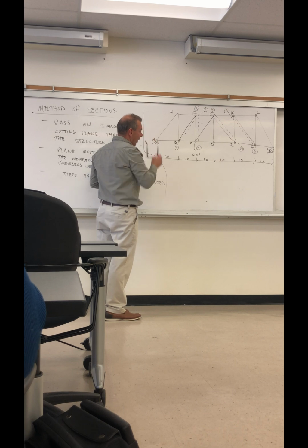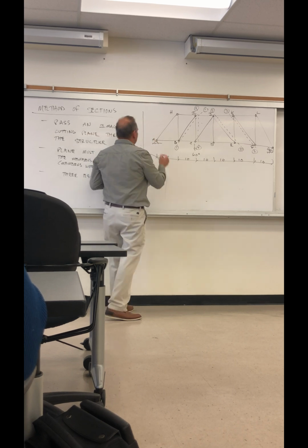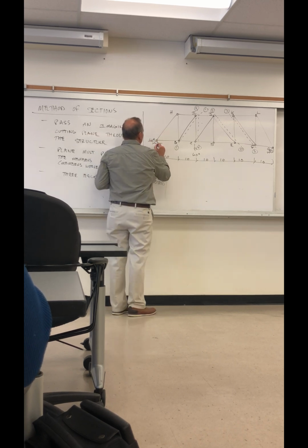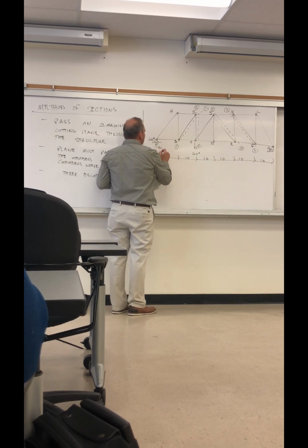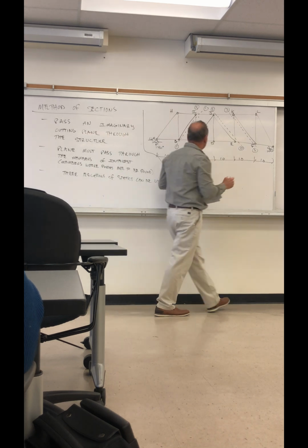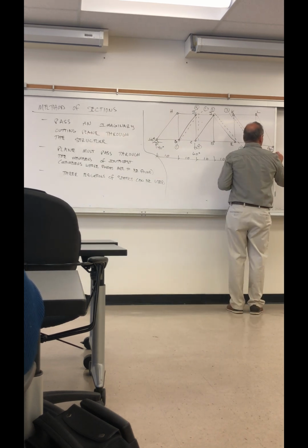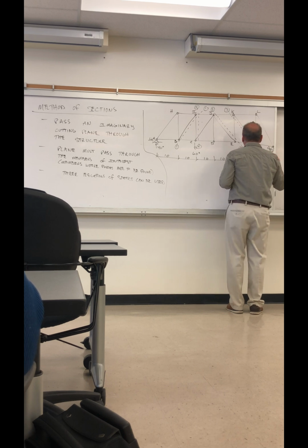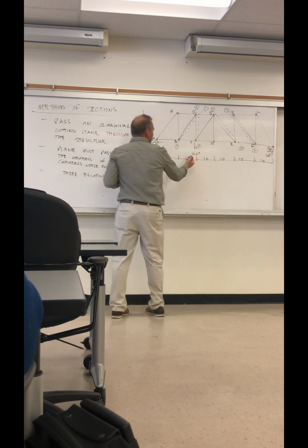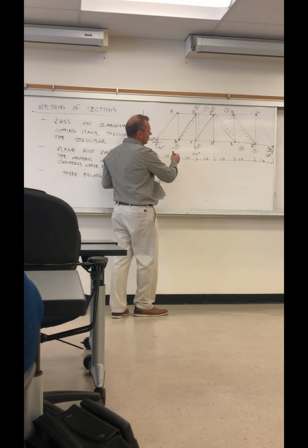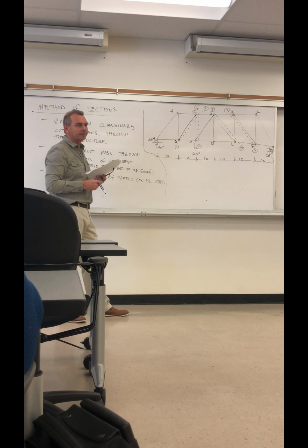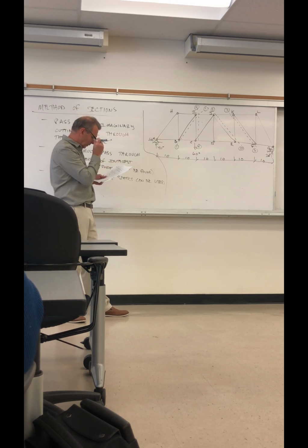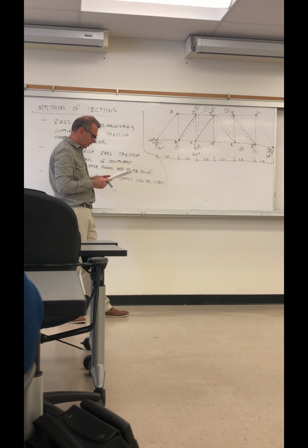Then let's solve for the reactions. This is 0. I sum moments about right. I get 40 kips here. And summing forces vertically at this point, 20 + 40 = 60. This 60 kips is not placed in the center, it's off center. So that's why there's a larger reaction to the left. Okay, so those reactions are solved in the normal way.